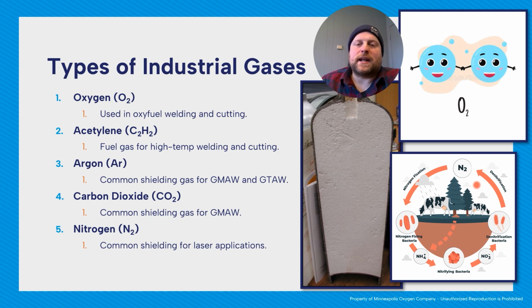But what it does is it can hold liquid. That's why perlite is in potting soil, because it can hold the liquid over extended periods of time. And the liquid that's in an acetylene container is acetone, the same thing you use to remove nail polish, that sort of thing. So the acetylene is kept in acetone as a mixture to stabilize the acetylene.